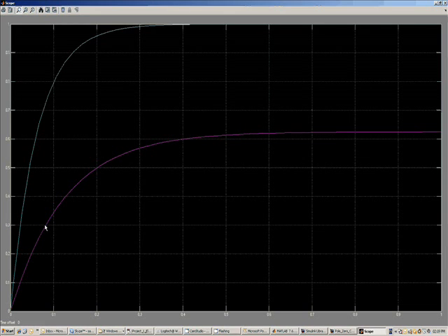Like this. So now you can see that roughly my time constant is about let's say 0.8 or something, and then I'll need a time constant of 0.4, and then now the output of the closed loop system goes exactly to 1, which is the steady state value of the input, which is good because there is no steady state error.